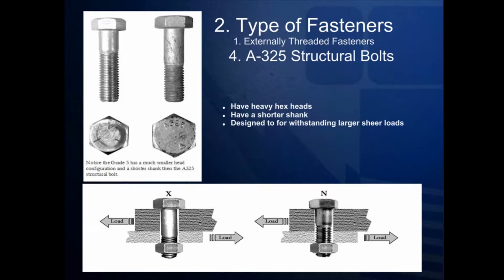If you can imagine, the forces applied in structural bolts are completely different than those found in piping applications. For example, the forces in a flange are actually pulling parallel with the length of the bolt. In contrast, structural bolts are actually dealing with a force called shear force. In shear force, they're actually going in opposite directions that are perpendicular to the length of the bolt. The chart on the bottom shows the differences of shear force when applied to a hex bolt versus a hex cap screw. As we mentioned earlier, the threads are the weakest part.